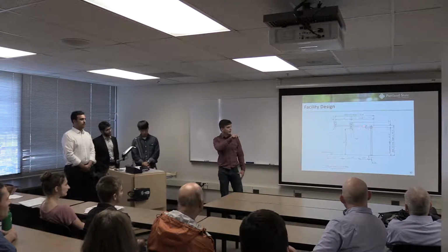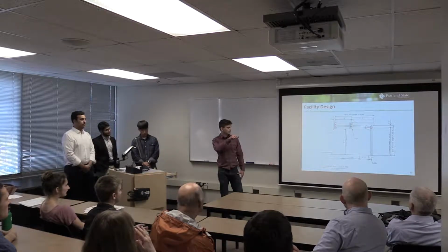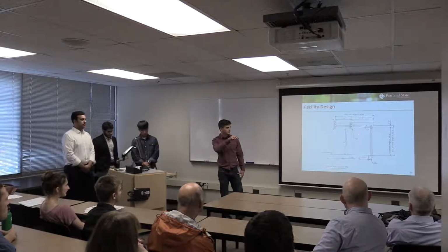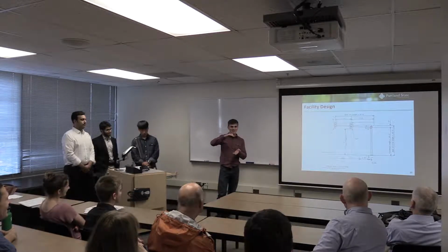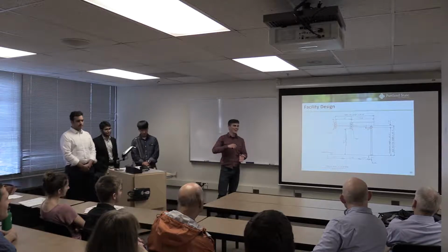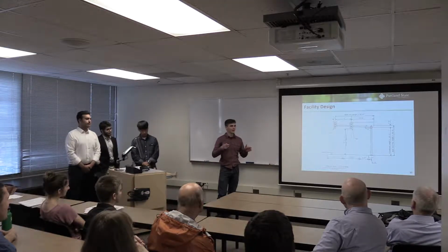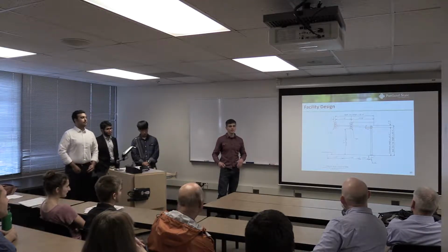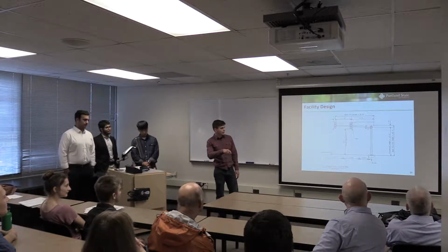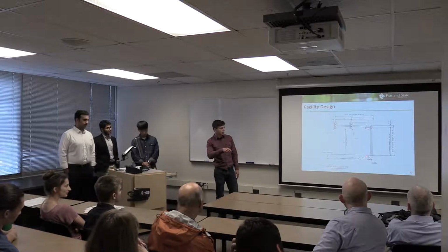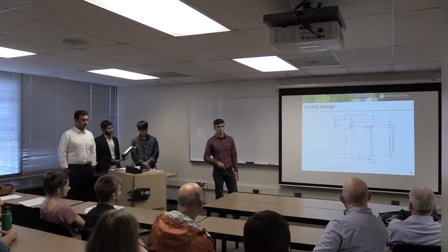On the mast arm, we're going to have attached 2 Type 2 standard traffic signals, and these will be centered in the lanes. This will meet the specifications on both height from signal head to roadway and in distance between each other for signal heads of the same phase. Also, the pole will be constructed 2 feet from the curb.